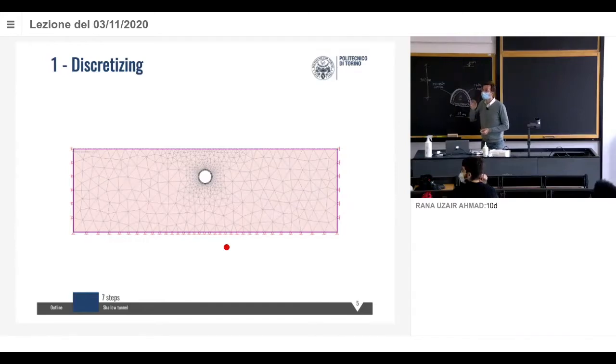Okay, so last time we probably said a good rule is that this is 14 meters. Since this is a deep tunnel, we can consider a model extended in any direction by at least 10 times the equivalent diameter: 140 meters on this side, 140 meters on this side, 140 meters and 140 meters, right?